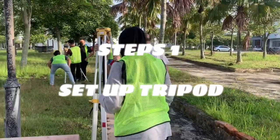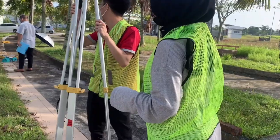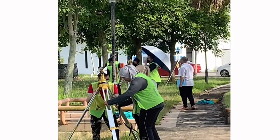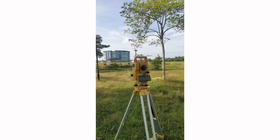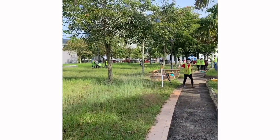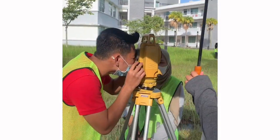Step 1. Set up the tripod. Set up the tripod on the station, open its legs and regulate the height so that it is approximately at chest level, and regulate it so that the floor seems flat. Step 2. Put the total station on the tripod. The total station device is positioned on the tripod, secured with a centering screw. While pressing the device with the other hand, insert the battery inside the device before leveling.